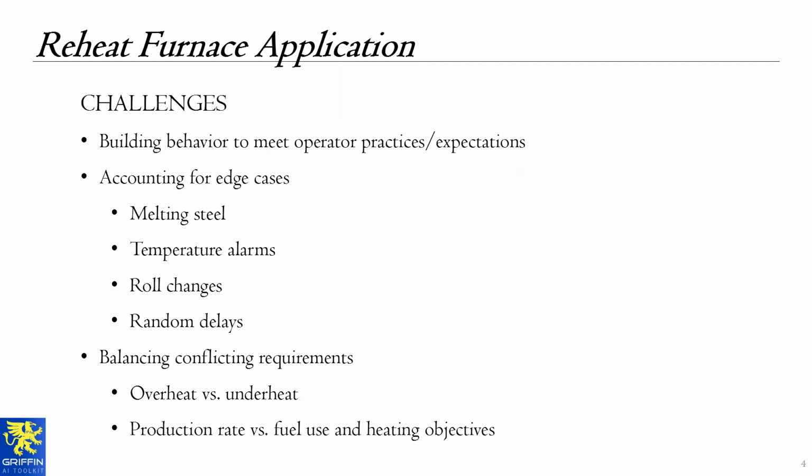Temperature alarms were another thing. I discovered some temperature alarms existed only after tripping them with my control system and kicking the furnaces out. So I had to make some changes, again, on the fly during production, to make sure that if we start approaching high recuperator temperatures, we're going to roll back on particular set points.